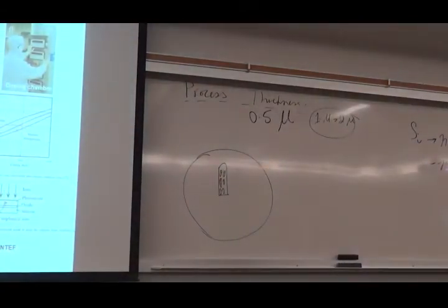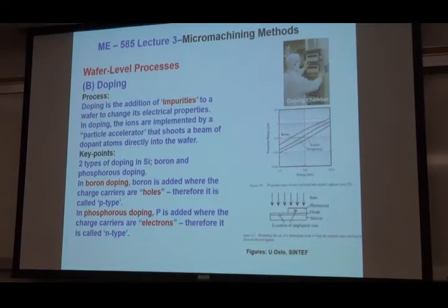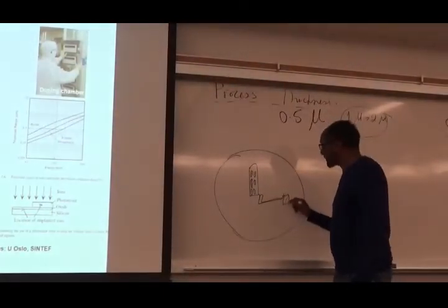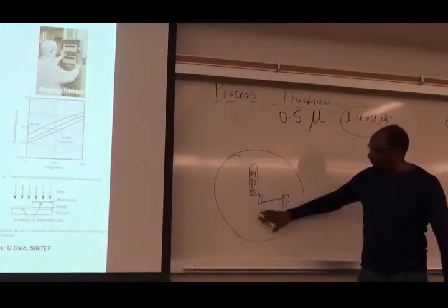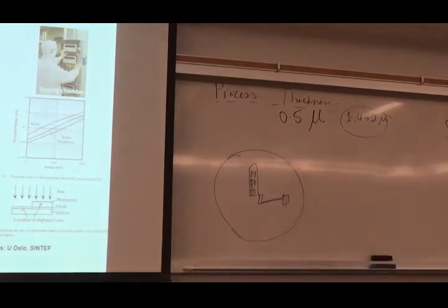So I'm going to repeat the same thing actually when I'm doing metallization. Because I don't want metal everywhere. I want metal only maybe a certain location. Like a trace here on a bump pad. So again, I'm going to do a lithography, put photoresist everywhere except here, and then I'm going to come and deposit metal. Okay? So this process is going to get repeated again and again, and finally we'll get a hang of it. And especially when you do, you'll see actually with your own eyes what it's going to look like.